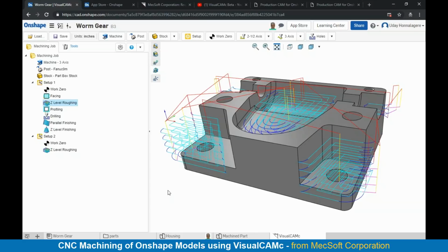Laser cutters. How does this work with the laser cutter? We currently do support it using the post-processors. We don't have a separate laser cutting method, but we can use profiling toolpaths and a special post-processor to handle that. So you need to create a 3D model out of it and then just do the profile cut or something like that, right? Yeah, so it'll work. Same thing with flame and same thing with water jets and all that.